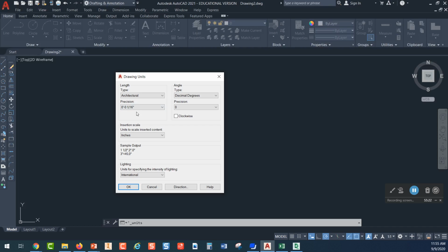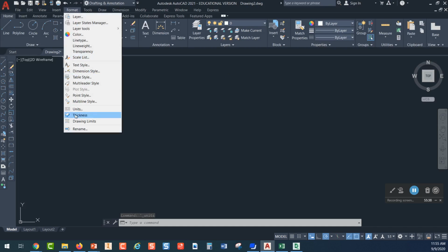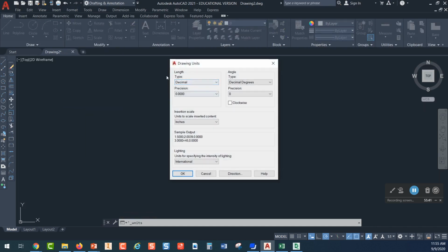So when you do the 3rd drawing that's going to be assigned today, it's called the guest cottage. It's going to tell you to go in and change your drawing units to architectural units. Okay. And so just as a reminder for how that's done, you go up to format and you go to units and you look at your type of unit and pick here and pick architecture. Now the book's going to tell you to do that, and I believe the video is going to show you again about how to do that. I didn't make that video, but I'm pretty sure she shows you how to do everything that's in the book on that.